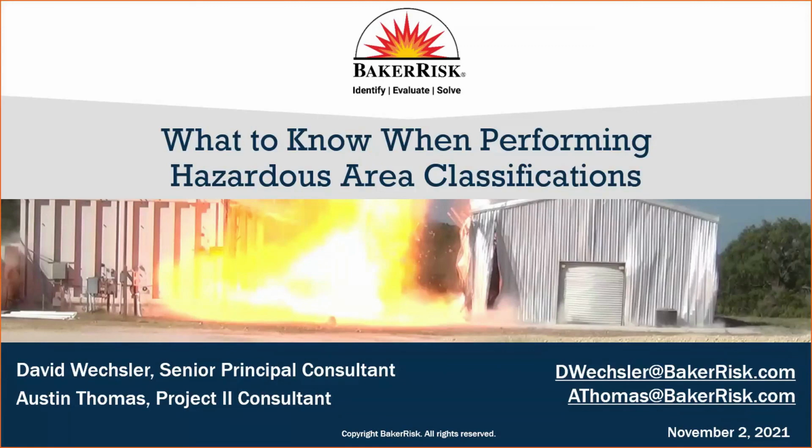Now, clearly this can be done if you're going to document things clearly and define why you're varying from standards and codes. But that's why I pointed out it's very important that when you apply the codes and standards, you pick the one that's applicable to your particular application. So if you're a distillation or a petroleum plant, you probably would want to use an API code rather than the NFPA 497 code. But again, it just depends. So again, choosing the appropriate criteria is going to help in making sure your base conditions are well established.